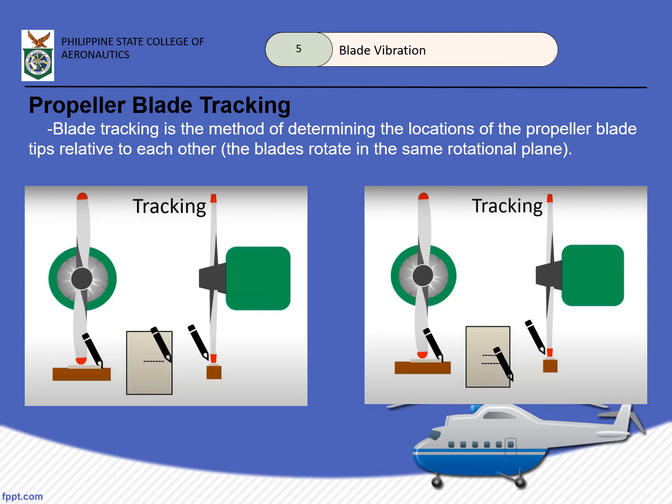So, with the reference point in place, let's rotate na the propeller blade. Tapos, imamark natin siya. The second photo, as an example, shows the mark for the track of the next blade. Diba, dun sa unang photo, minark natin siya, then we spin it, then we mark it again, in order for us to have a certain comparison.